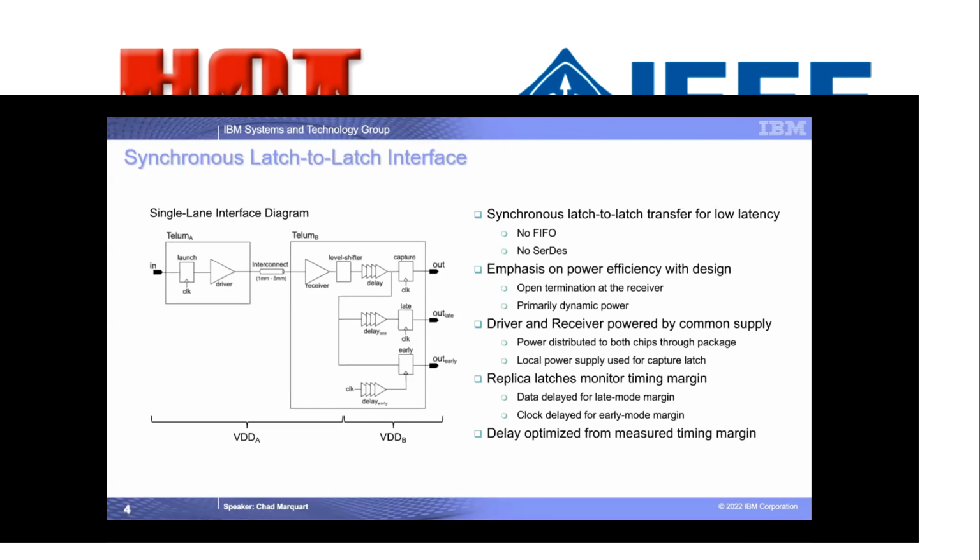Probably one of the biggest factors towards the power efficiency is the use of an open termination at the receiver. Without a low impedance termination there, constantly drawing DC power, the majority of the power is dynamic, so it will scale with voltage and frequency.